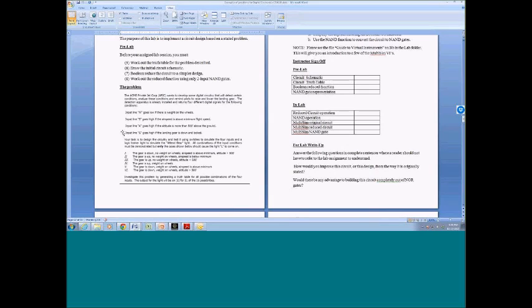And there's some ways to save chips if you use XORs or something like this. But basically what I'm saying right now is, is there a way to make this better if you change some of the inputs? Like right now it says the input line S goes high if the airspeed's above a flight speed. Well, what happens if you reverse that? If S goes high if it's below the flight speed, does that maybe give you K-maps which reduce even further?